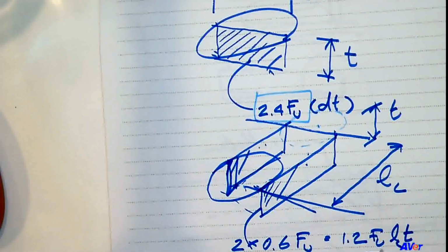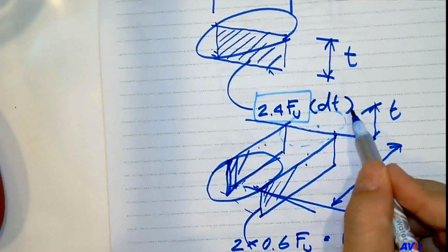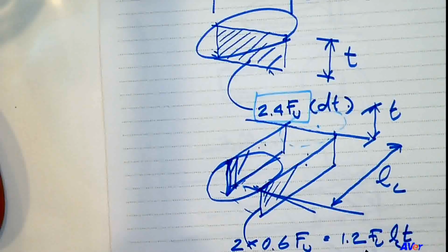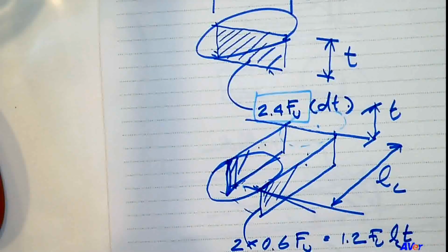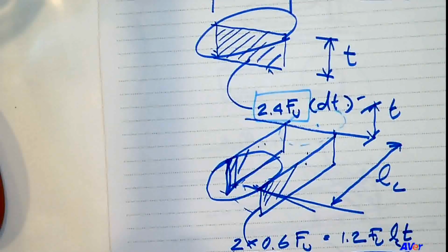On the other hand, if I check and this bearing number is lower than tear out, the bearing failure may occur before the tear out. And this becomes the strength of that bolt hole at that particular point. So it's either one of them.